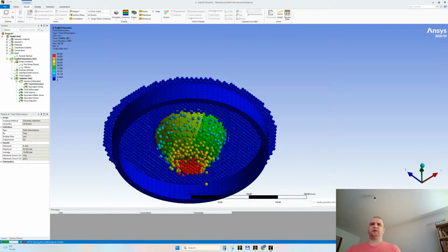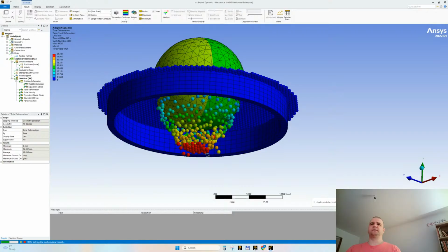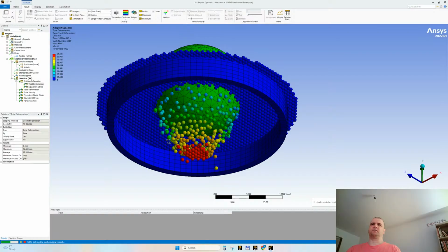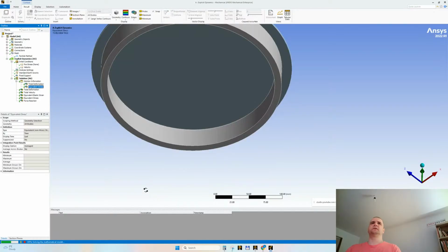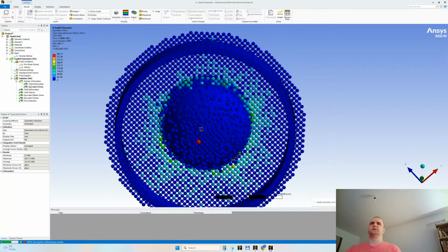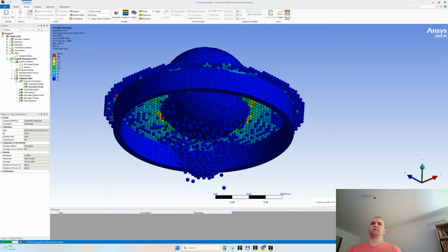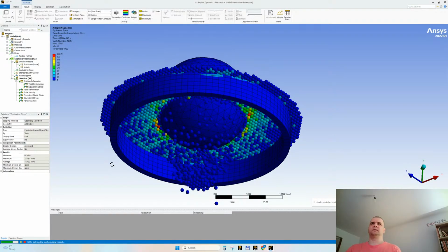we do have breakage here, but the deformation is localized. We would have expected some creases, some cracks to appear. This means that it's not covering so well the reality of the simulation. Now regarding the stress, it's much nicer. But the behavior, we can say it's not correct. Let me show you what needs to be done.